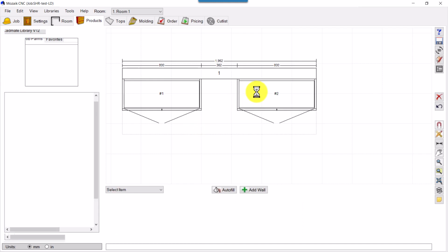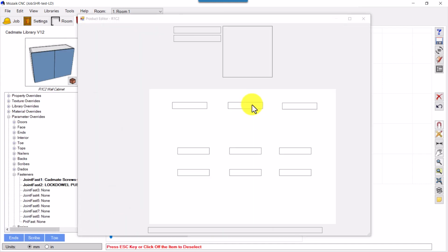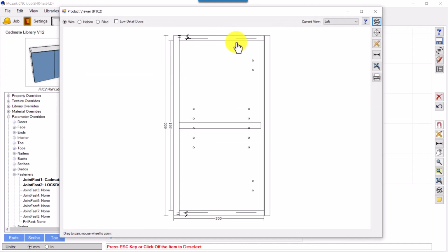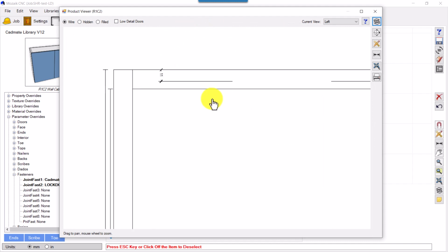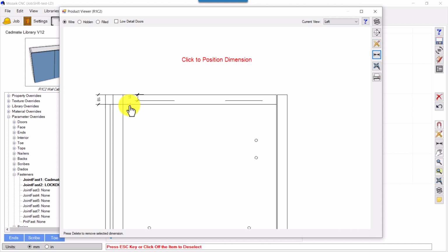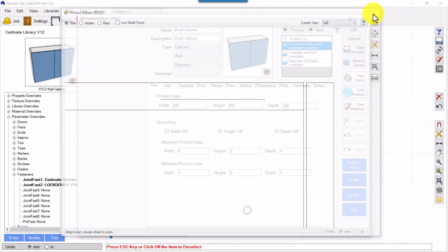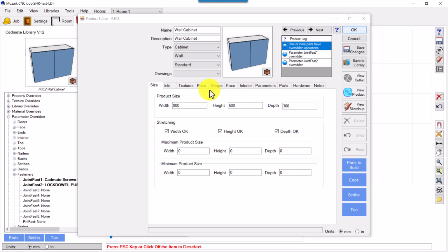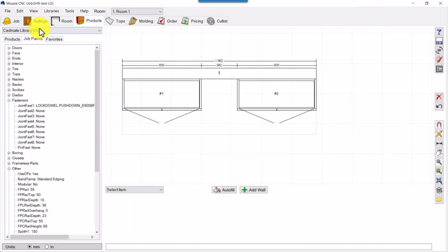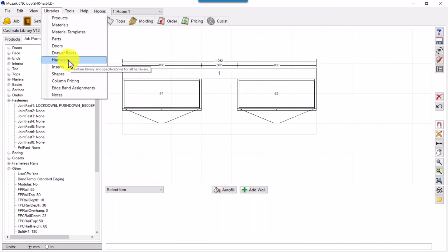So now if we check this here, see, we have this 18 mil thickness board top panel, and we offset that route path successfully from the top by 11 millimeters, right? So there is a simple trick to achieve this. I'll compare both the settings so you will understand here.